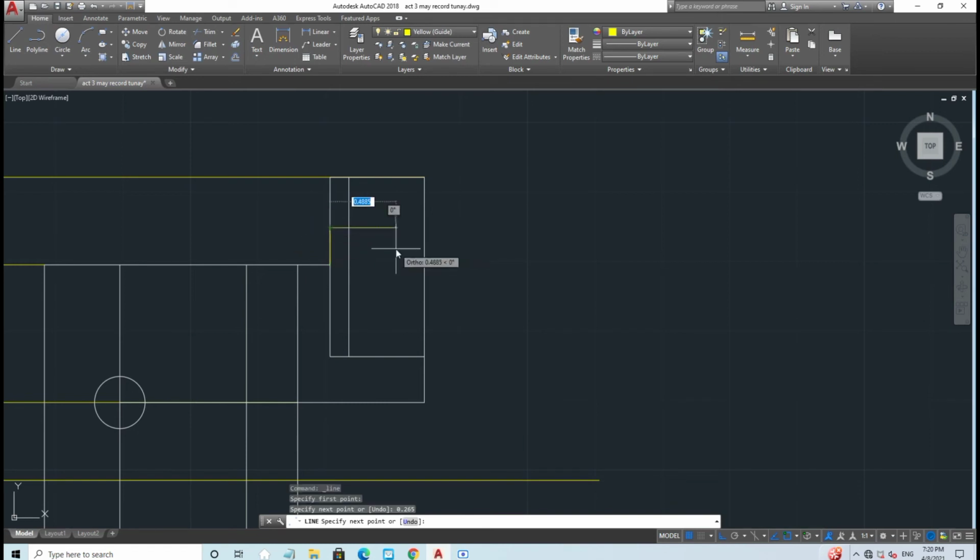0.265. Turn this into normal and create a line, a horizontal line measuring to the left measuring 0.62 and connect it into this point or line, then escape. Extend this line up to here.